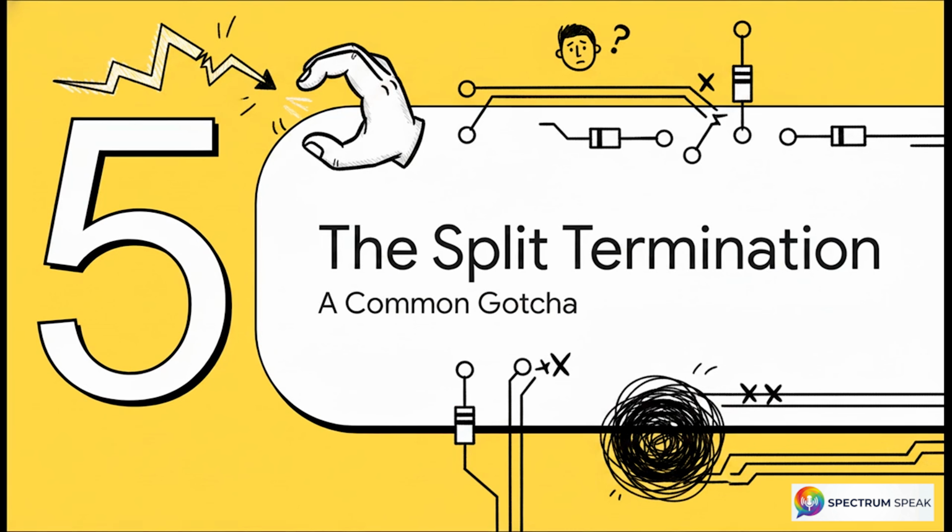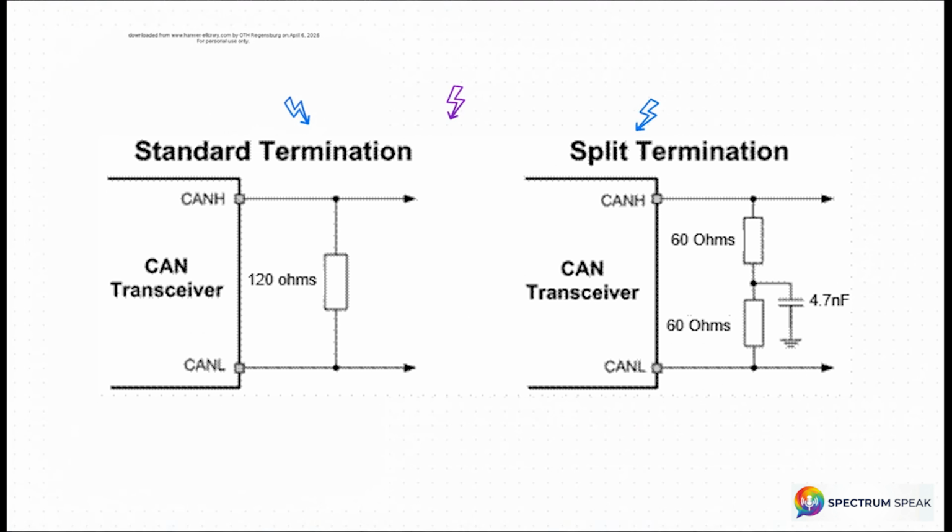Which naturally leads us into Section 5, the split termination gotcha. This right here is the physical layer pitfall that ruins countless engineering projects. Think about it. If you turn off transistors T1 and T2, how do the CAN high and CAN low lines actually get back to their 2.5-volt resting state? They need a path for the electrical potential to equalize. This is exactly why termination resistors at both ends of your CAN bus are absolutely mandatory.